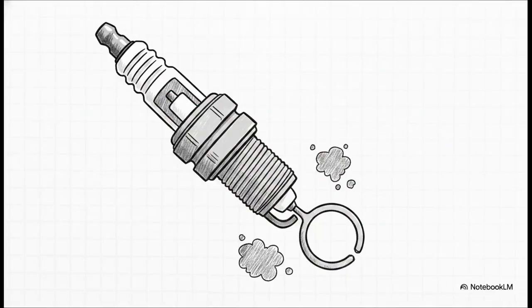Of course, all that intense, high-voltage energy ultimately ends up at the spark plug. And in this course, you'll learn that maintaining those spark plugs is basically an ongoing battle against extreme environmental degradation. We're going to dive into their internal ceramic insulator architecture. We'll evaluate heat range classifications. You'll even be in the workshop diagnosing fouling from carbon, oil, and lead deposits. Oh, and you'll learn the specific technique for measuring spark gap erosion using a round wire thickness gauge. Why round? Because a flat gauge simply won't give you an accurate reading on a contoured electrode.